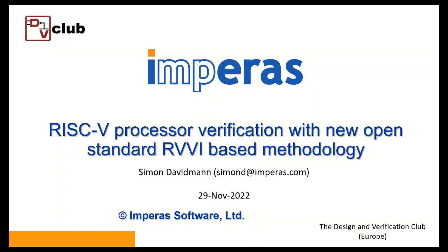If you want to do full DV, then you need to license in some technology, for example, like our RISC-V stuff. But if you want to do earlier stuff like trace checking, you can get the RVVI working, and then you can add a trace component to it. At the moment, as RVVI is just starting, there's very little yet available. But you could build a trace and make it publicly available. Anybody could use it. We expect those collaborations to happen. We provide some currently; they're proprietary. But over time, we expect them to be more open and open source.